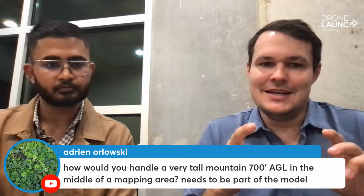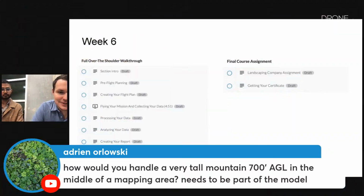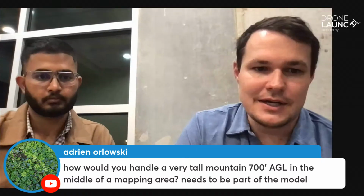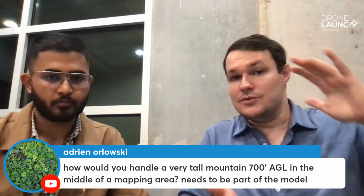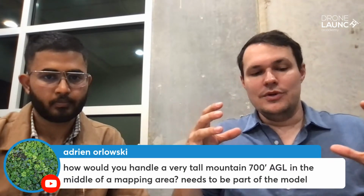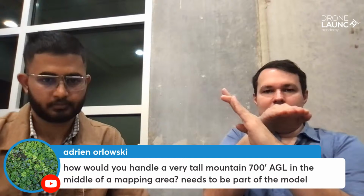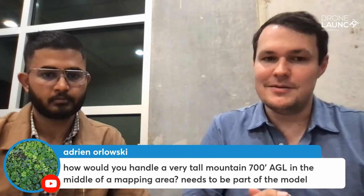We talk about this in the data acquisition fundamentals. Real quick, I gotta show you this right here. Hold on. If you look right here, it's gonna be hard to see, but in the middle, how to handle changing ground elevations. We did a 10-minute video on this, so I'm gonna give you a little sneak peek. So you can either do terrain awareness, where you're staying the same distance over the mountain the whole time, which is preferred. If you can't do the terrain awareness, the best way is to split the job up into chunks. So if this is the mountain, you're doing some here, and some here, and then you would process all those images as one map. So that's a less preferred method, but you can do that.